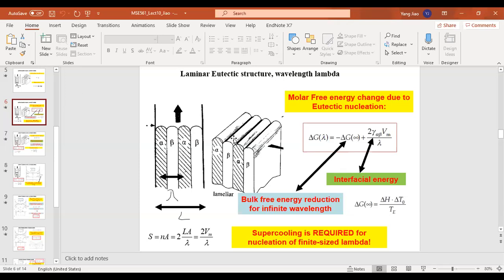Another distinction is that the growth of these small nuclei is not isotropic. Okay, so in nucleation processes where you have a spherical nucleus, we know the nucleus is simply going to grow in size. And for a long time, we can approximately consider the nucleus to remain a circle or sphere in 3 dimensions. But here, as we demonstrated, the growth of the nucleus is basically along one direction. So the alpha and beta, these very thin layers of different solid phases, do not grow in their thickness, right? They just grow in length. So basically, they propagate in this direction.